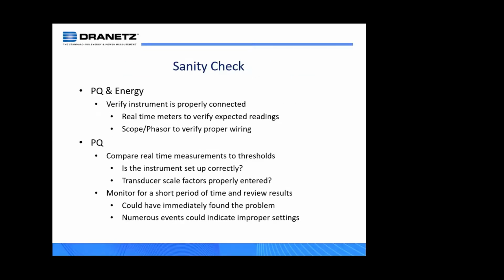And then there's the sanity check. Before you walk away from the instrument, the sanity check would involve: are we reading the right voltage values? Are we reading the right current? Do we have reverse polarity on any of the probes? So you use features like scope mode, the phasor display, to verify proper wiring. This is probably the most important.